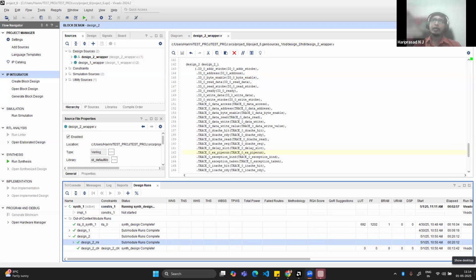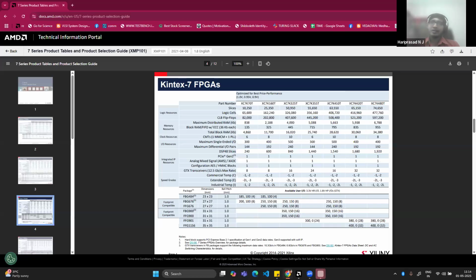So depending on your application, for what purpose you are using, according to that you have to choose the DSP, right? Ideally, before buying an FPGA, first we have to synthesize. During synthesis, you need not buy any FPGA. Then you go to this table and choose. Let's say your design is taking 1000 DSP, then this device is ruled out. This device will not support it, and till here it doesn't support. You have to go for the 1440 device, right?